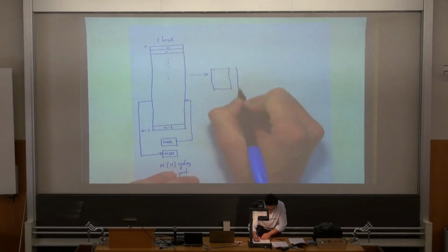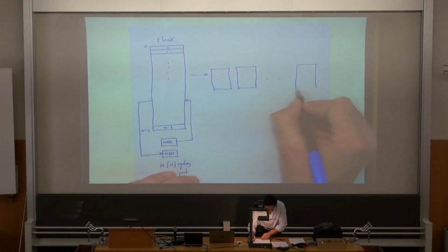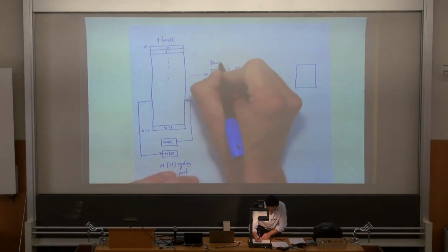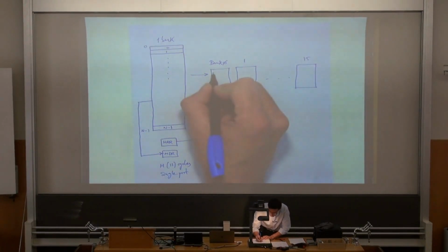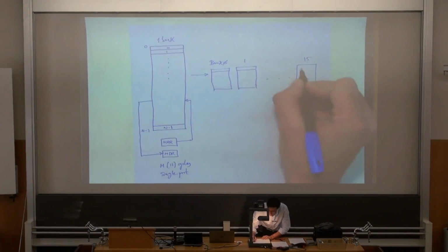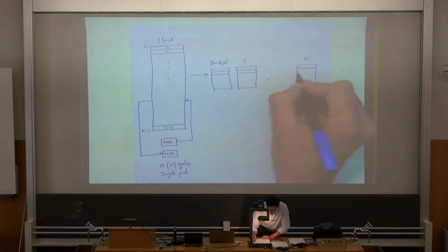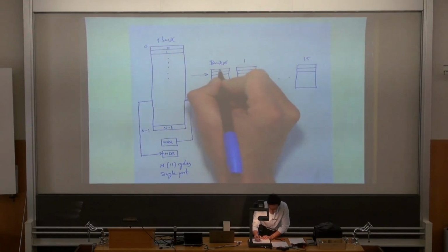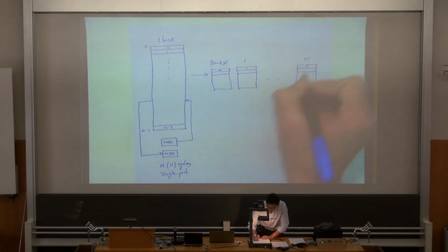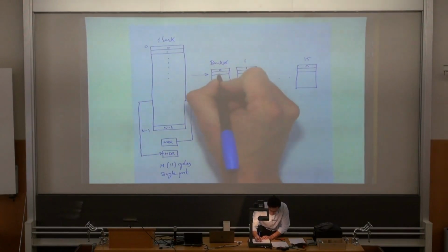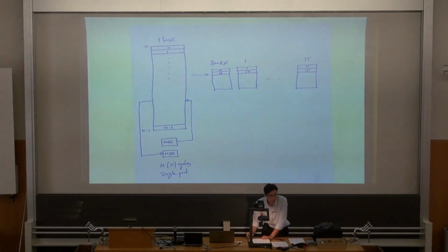What we can do in order to have a more efficient access to this memory is dividing this memory into banks. In our example, we are using 16 banks. This is bank 0, bank 1, bank 15. Now what we do is storing the values corresponding to the different addresses in an interleaved manner, so that address 0 is in bank 0, address 1 is in bank 1, address 15 is in bank 15, and address 16 is again in bank 0, and this would be address 31.